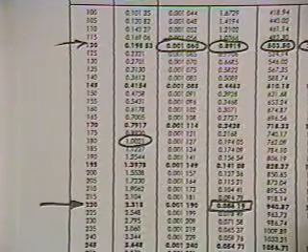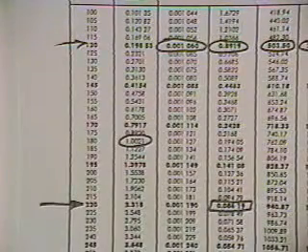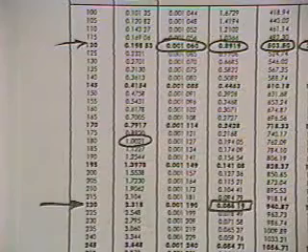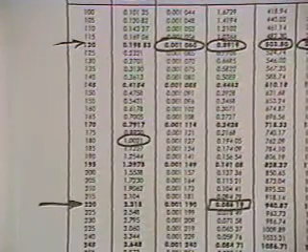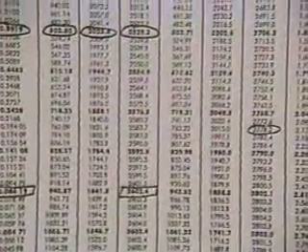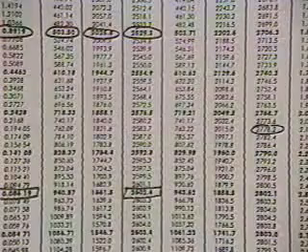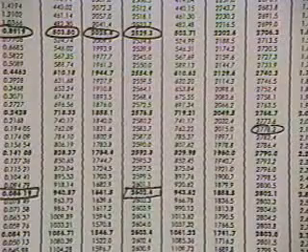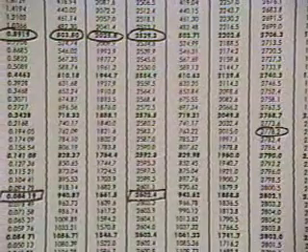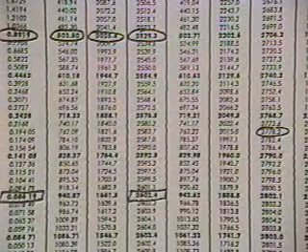1.002 will provide you an enthalpy value that'll be close enough to what you can work on the exam. So you come over to the saturation conditions, and you see that you've got a value of 2778.2 for the enthalpy at 1.0021 megapascals, which is close enough to 1 megapascal for us to solve the problem.